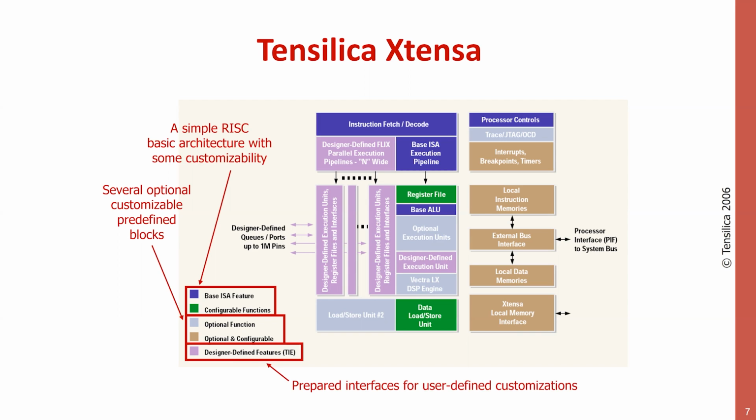And then it opened to a third part, which is actually something that is not designed at all, and is something that you write yourself. So essentially, you have some interfaces to circuitry where you do what you want. So you have here, for instance, a user-defined execution unit, something that takes maybe 2 operands from the register file, does something that probably is not the multiplication, the addition, the classic things that you think of, and produces a result and puts it back in the register file.